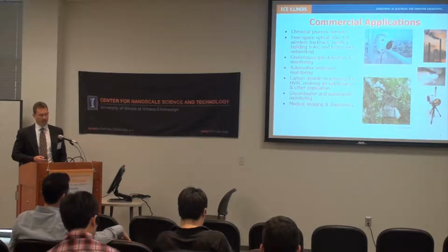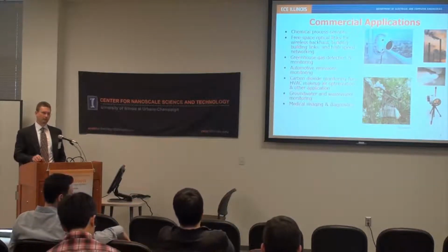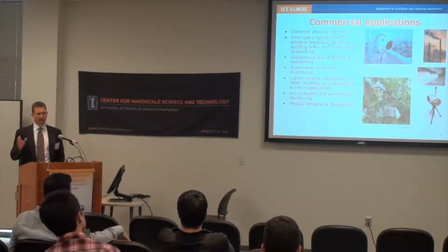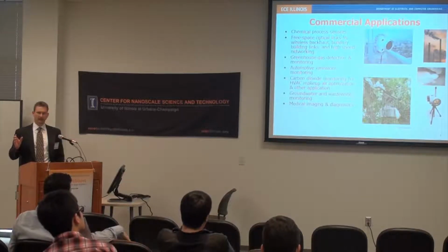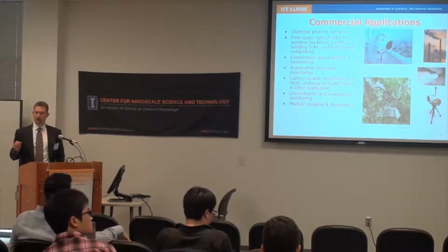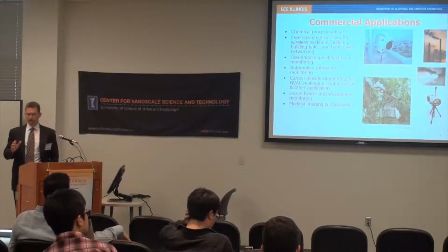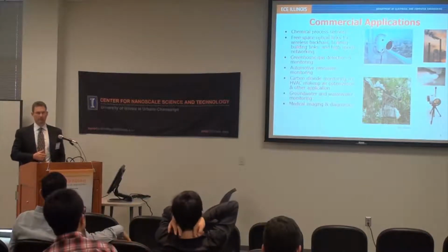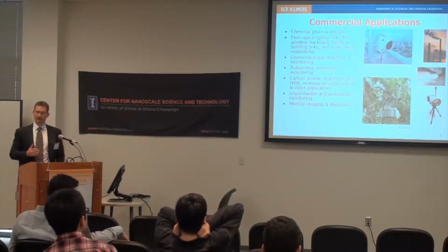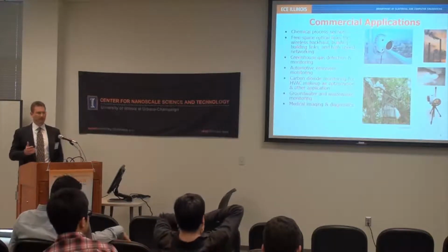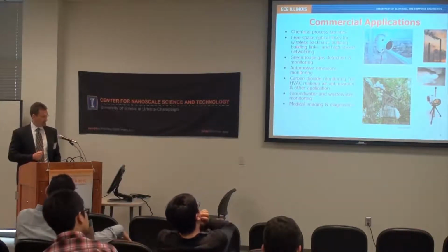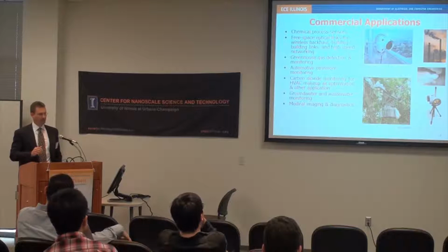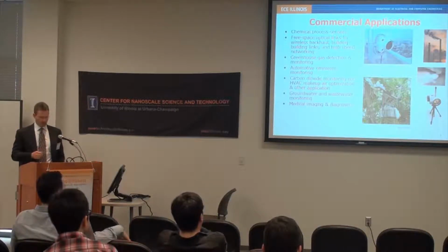All of those applications become very important, especially for a device where you can move on to or around a given chemical transition and dither the device wavelength around that in order to look for amplitude changes near a specific wavelength. That's one of the things that we feel we can do with this device, and rather than relying on device heating, which is a slow process and more typical for the quantum cascade laser, we can do it by a fairly rapid modulation of what ultimately is our base-collector junction in our transistor.